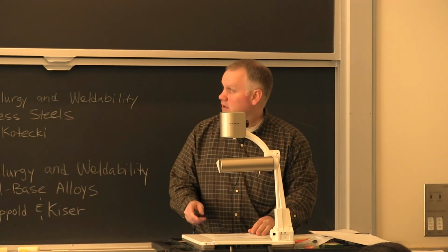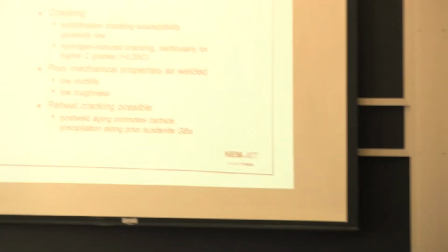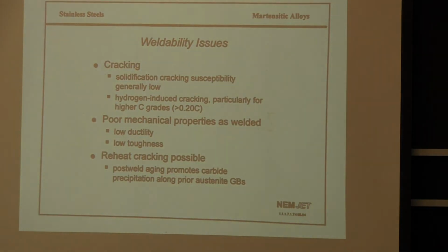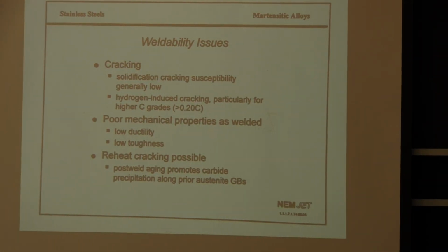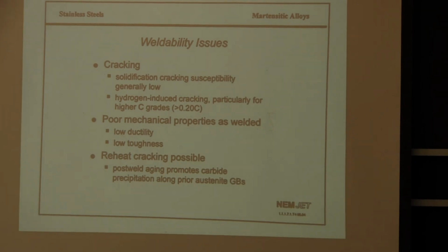So just continuing along the lines of weldability of the martensitic alloys, as far as cracking goes, solidification cracking susceptibility is generally low in these alloys, but the main concern as far as cracking is the hydrogen-induced cracking, particularly for the higher carbon grades.